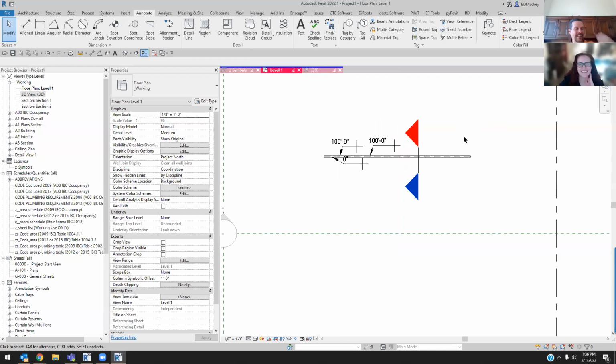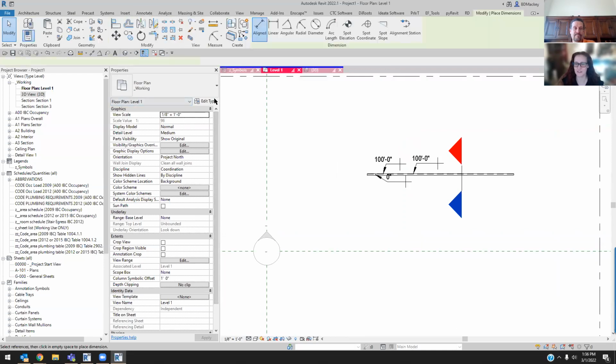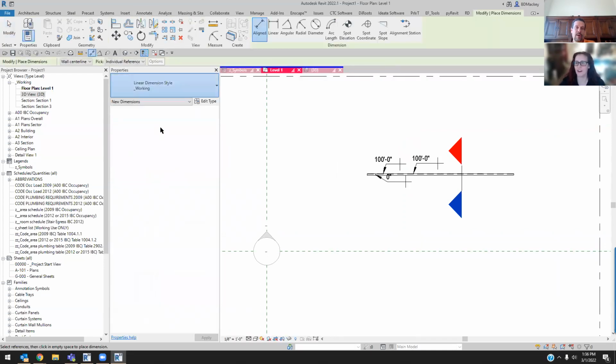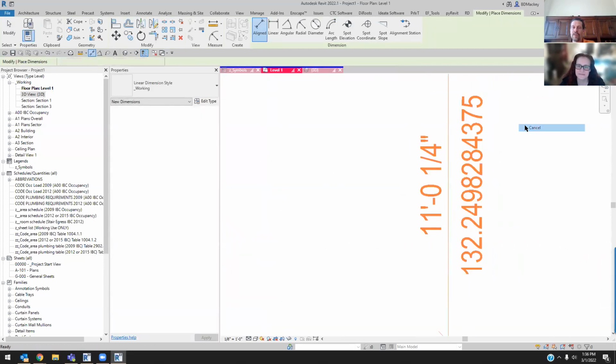0.00001. I don't think 0.0001 would actually change those numbers, because that's such a slight rotation. Revit can only go out so far. If I was in decimal inches and went out to like 10 decimal points it would, but at 1/256 of an inch, you're not going to see that. Yeah, in our template, we do have a very high tolerance made to catch the 0.00 whatever off. My working dimension is very similar. So you get that, because even though it says 11 1/4, that's not 11 1/4.